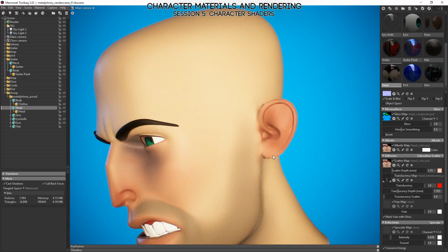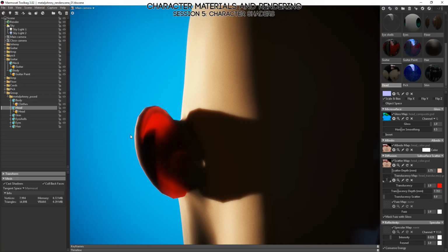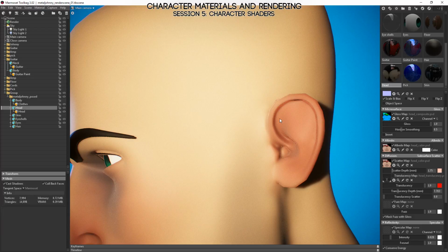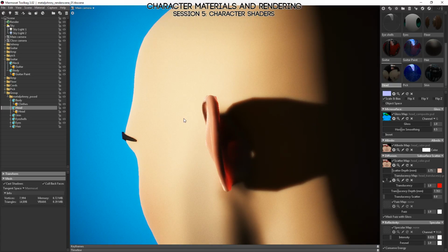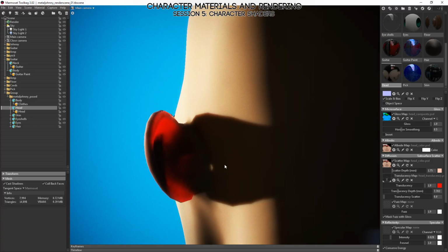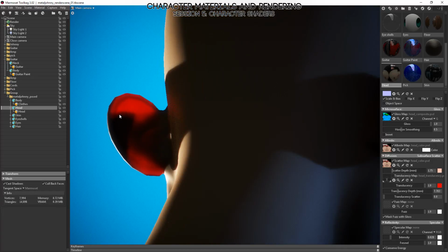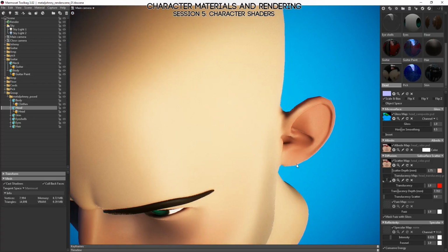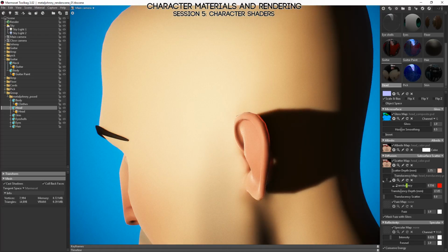So some of the light certainly will hit and then shoot right back towards your eyeball or the camera, but since some of it is going through and taking on this color, or some of it is just being absorbed, it means that the color coming back to your eyes is going to be modified according to whatever this transmission color is. So the color that comes out, depending upon the viewing angle, is going to be different. So the more it's facing away from the camera, the redder it's going to be, and the more it's facing towards the camera, the cooler it's going to be in general. So let's turn that down a little bit.